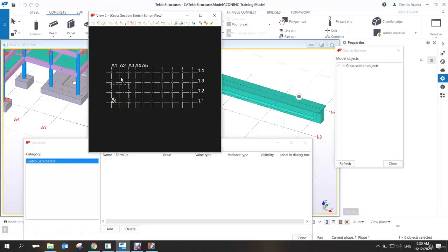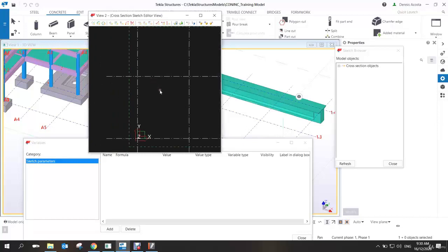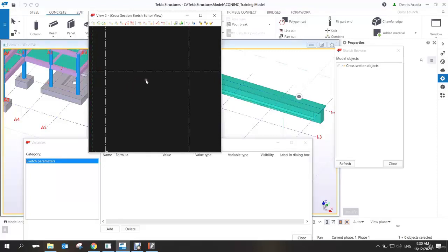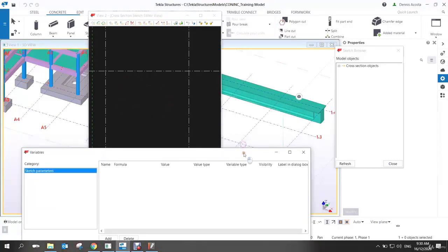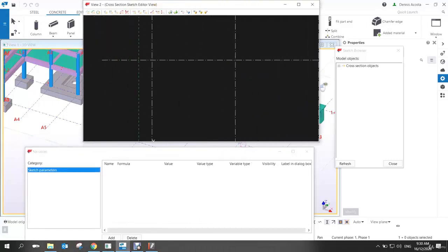That's why when you are creating a small profile, don't pick grid to grid, because when you save that one, the profile is big. So you can just simply assume the place. See, this one is 5 meters. So meaning, if that one is 5 meters, this one is 3.9. So meaning the sketch will be somewhere in the middle.